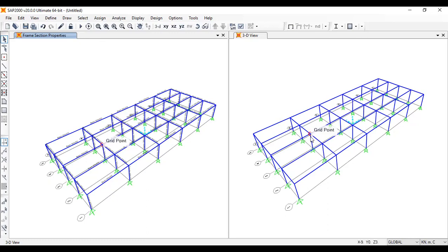In that case, you have to model it and select a rigid diaphragm. In MIDAS, there are options to select rigid diaphragm. In such case, you need to draw a sample slab and then it will be a rigid diaphragm because everything is connected together. It will move laterally. So one thing is how to idealize the real condition to the mathematical model, so the FEM model.